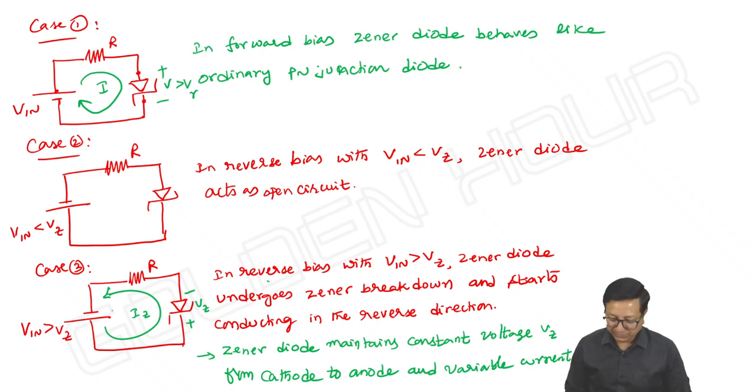Now if you take this particular circuit and take the loop equation, what we can write is minus V in, or plus V in also, it doesn't matter, plus Vz plus Iz into R is equal to 0. And the same circuit I'm rewriting like this.